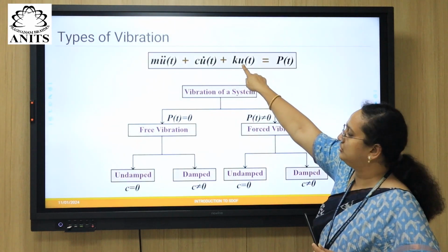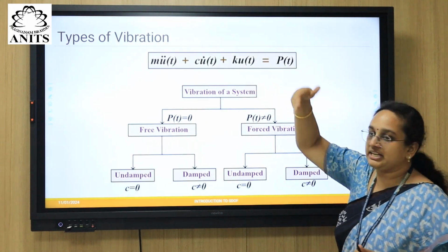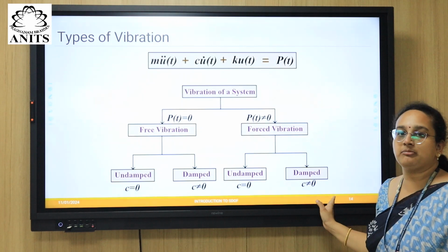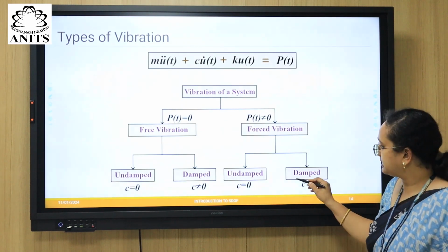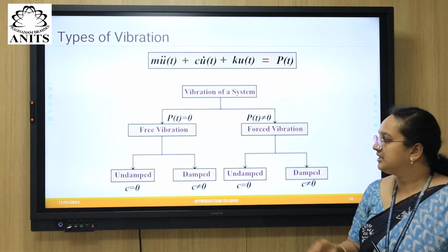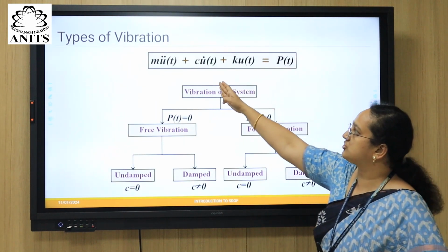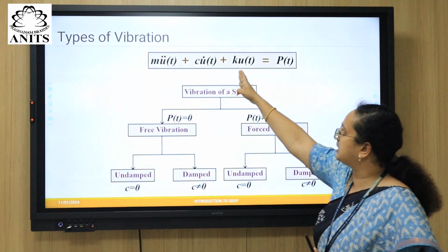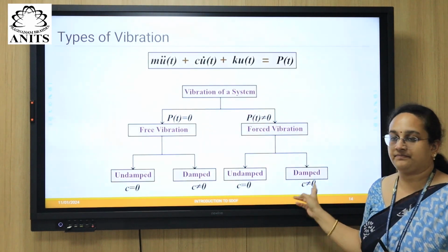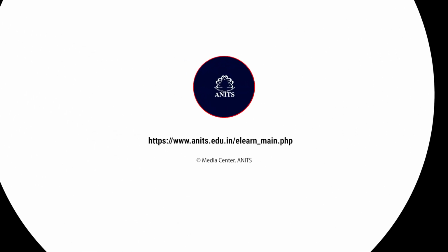Now to get u, that is the displacement at each and every time step, we need to get, in each case, what will be the solution, right? As I have told you, everything results in a closed form solution, right? So we can discuss the solution of this dynamic equilibrium equation in all the 4 cases.